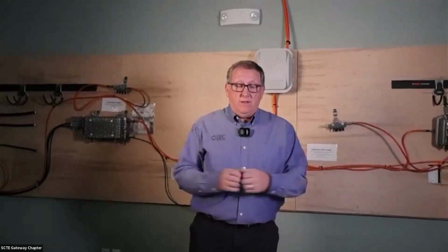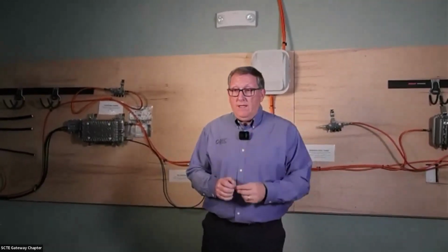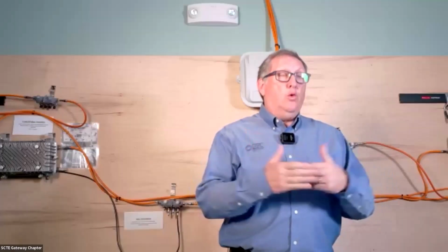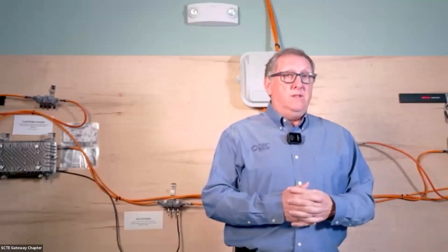Everything we're looking at, drops and things, is all single mode fiber. Is that correct? Yes, they're all single mode. Most of the time they use single mode fiber. Multi-mode, as we talked a little bit about before, inside a data center environment, the core is 50 microns wide, designed for short runs of multiple wavelengths. So we don't use multi-mode usually in any environment other than inside a data center.